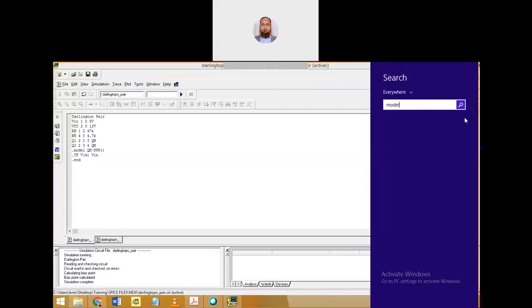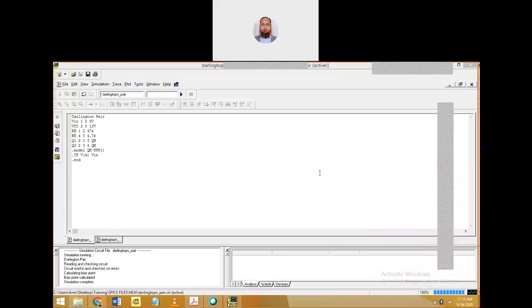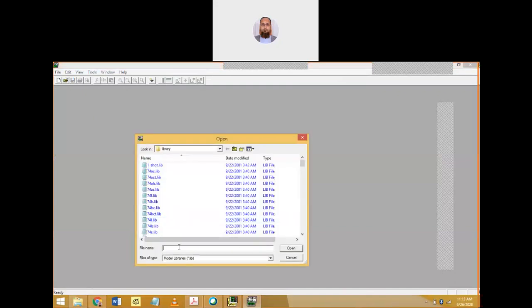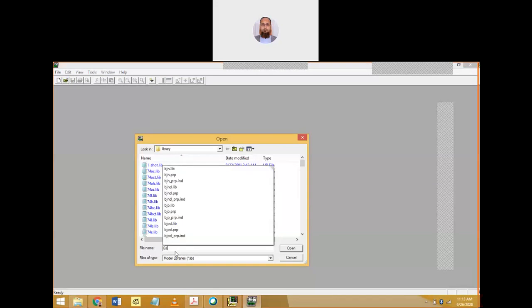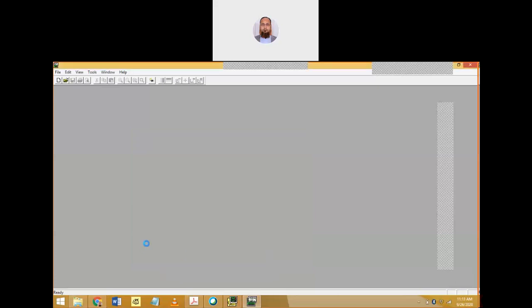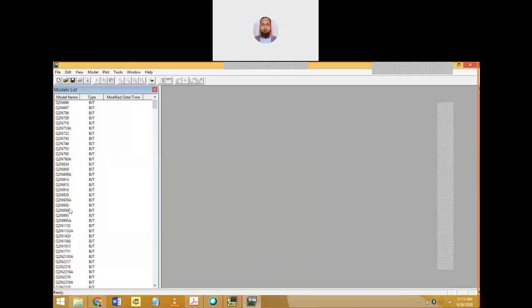So this is the model editor. Open this. What we want to see is BJT, so let's say I click BJT. BJT directly did not come, so let's say bipolar, bipolar dot lib. You can see that so many models of the BJT are there.